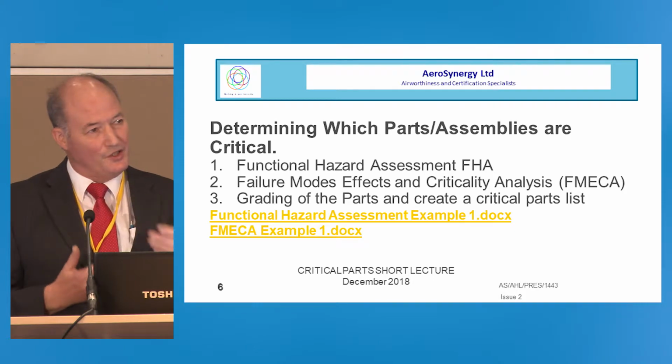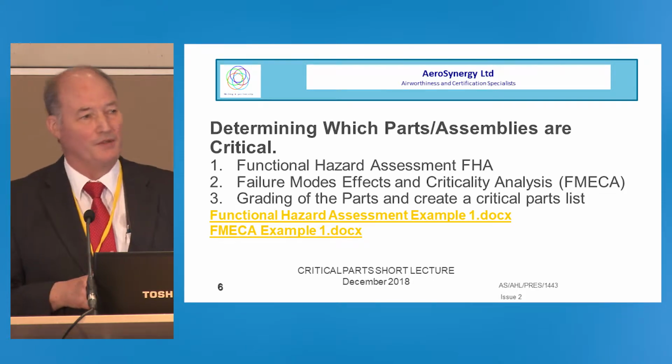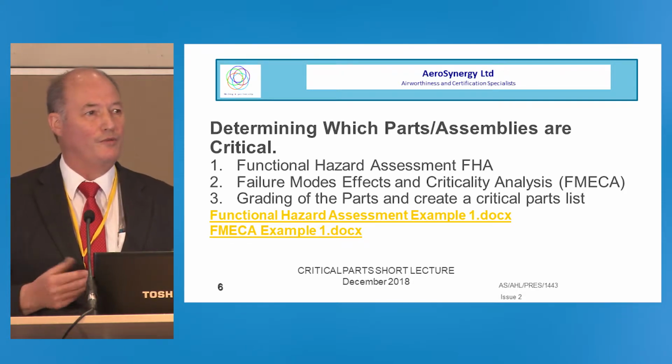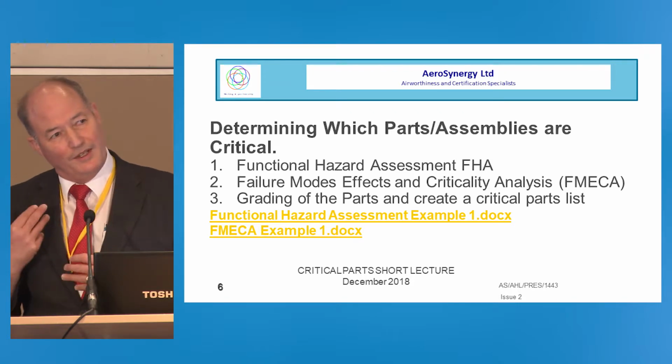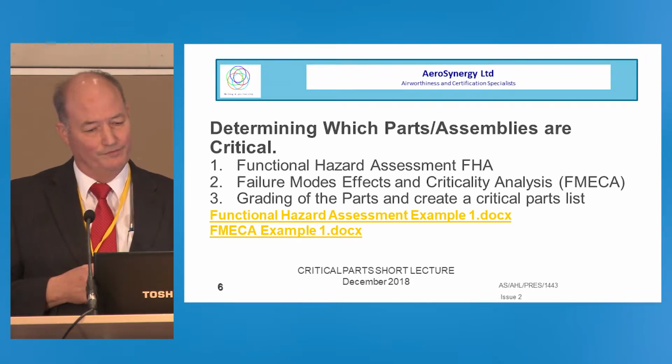And so for each possible failure mode of the subsystem, be it something like a gearbox, a rotor, you categorize the failure mode. We then do something called a FMECA, failure mode effects and criticality analysis, where you look at every part in the subsystem, and I do mean every part, not just the major parts. You even sweep up all of the fasteners, etc., and consider all of those and think, what happens if they fail?